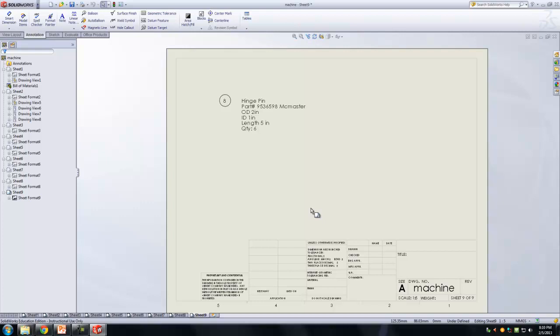So, create the assembly. From that assembly, you create a BOM. From that BOM, you do an auto balloon, and you just create the sheets after that. That should have the smart dimensioning on them, and the last sheet would be the standard part sheets.